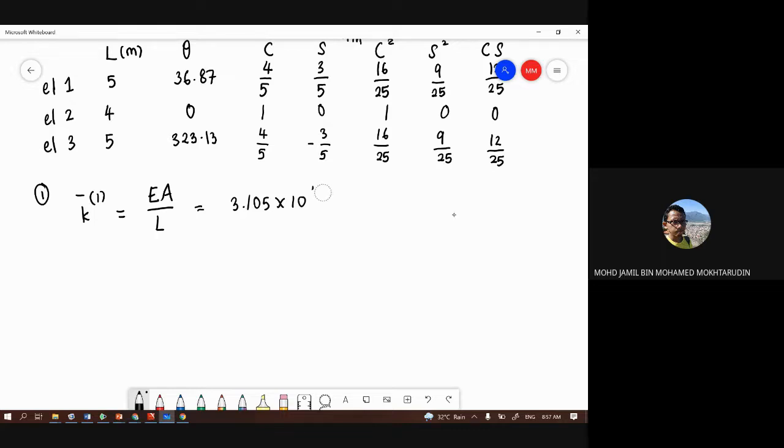Okay, so convert the length to millimeter to make sure that you use a similar SI unit. It's better to keep the SI unit in millimeter because usually the displacement is very small in truss elements, so your answer will be in kind of whole numbers if you use millimeter.